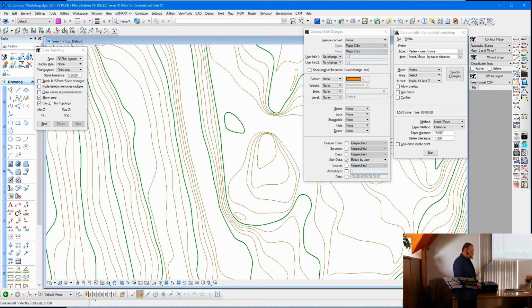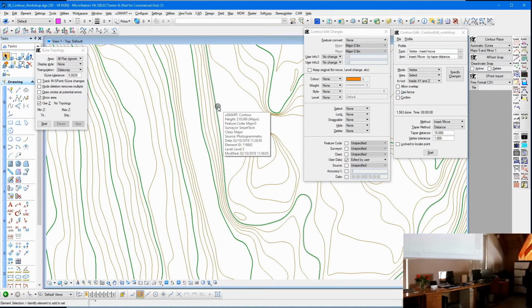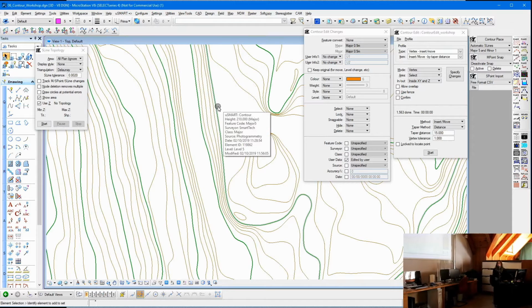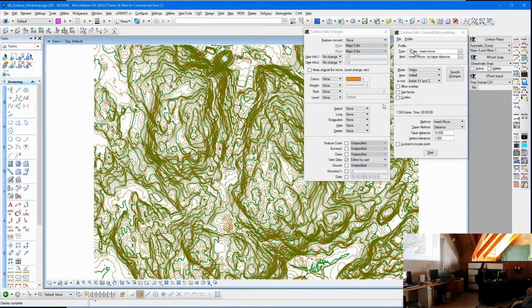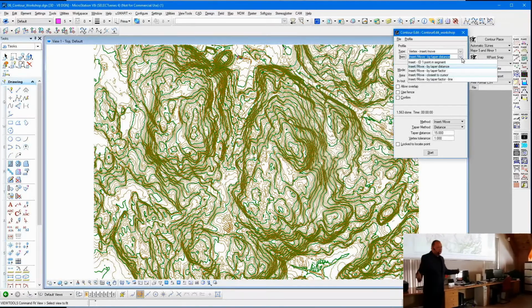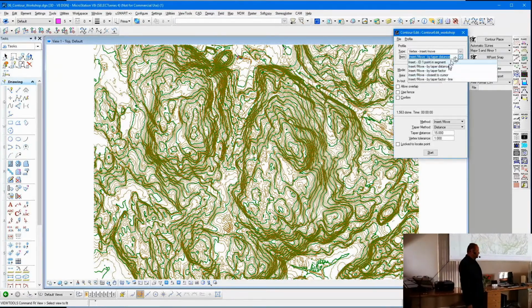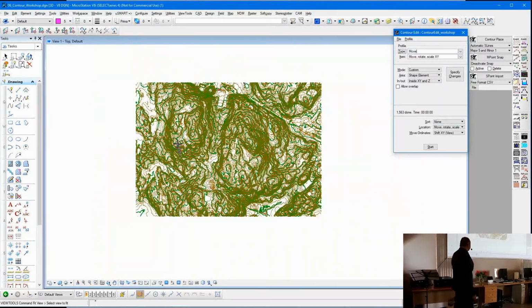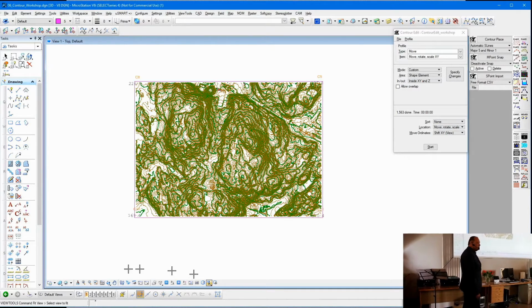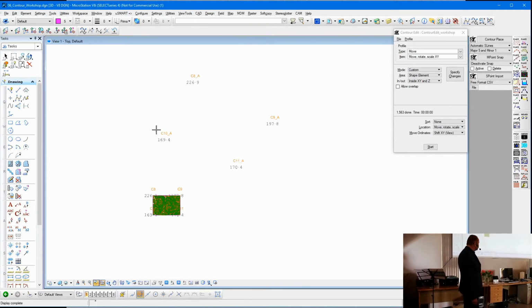So I just added the metadata. And then we just want to do that move, the big move. At this point in time, we did a local survey, okay, and now we get some control and we want to bring it onto the national grid. So we've got this whole area here, for example, and we're going to switch on some control points that are common to both systems. And so here we have some points, and you can see we've got quite a radical rotation and scaling over there.